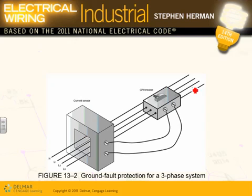Here's my phase ABC. Suppose I have a ground fault in the system. So I have 100 amp here, 100 amp here, and let's just say here I have 80 amps. Can you guys see that? This phase has 80 amps. And then the neutral, you have to do your math. The neutral is going to be carrying current. Say I have 20 amps in the neutral.